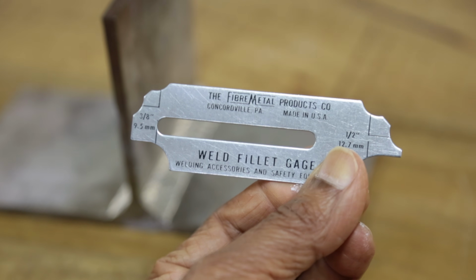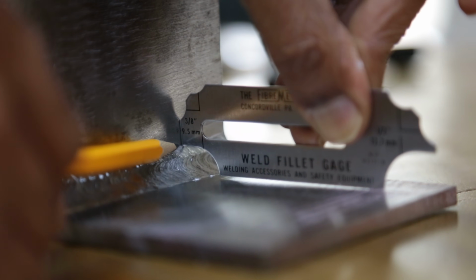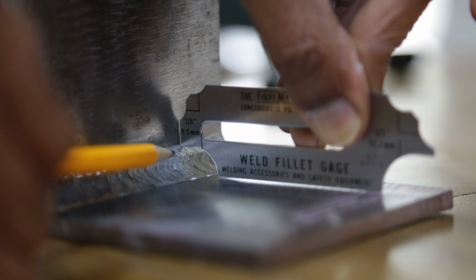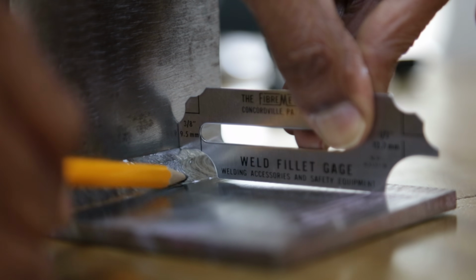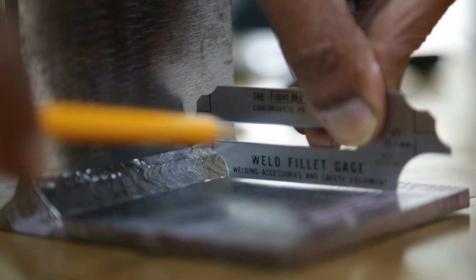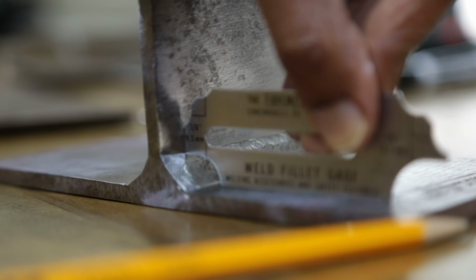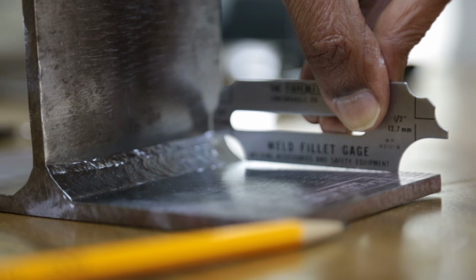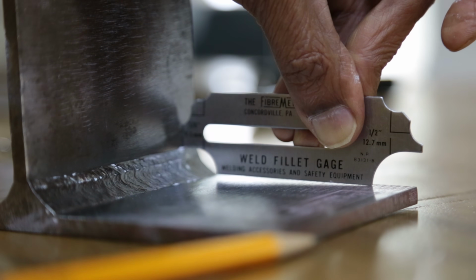I'll give you a demonstration, and you put it here like that. And then you will make sure that this top tip is kind of getting lifted up. So that's a good sign. That means that's enough leg, which is more than the size. And then this line here, you can extend it to the bottom here, and make sure that leg is more than that extension of the line. And then you can go through it all over like that to make sure. So the leg of this weld is acceptable. It meets the size requirement.